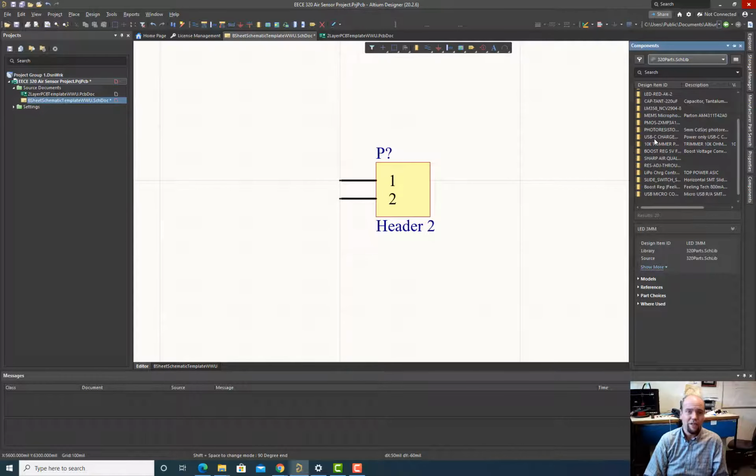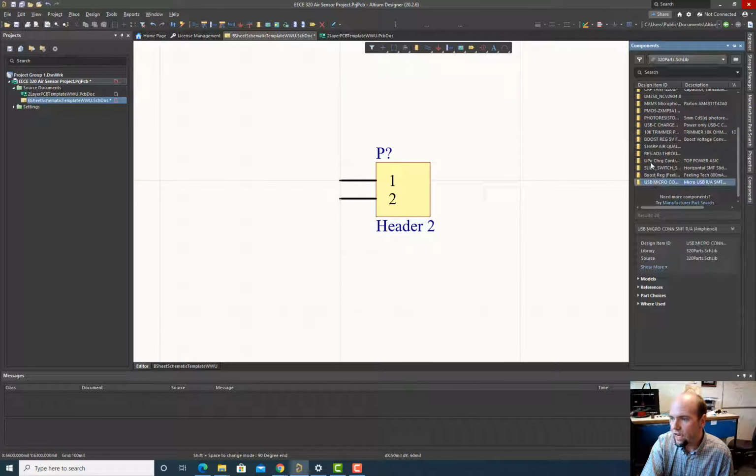So we could just take the USB-C connector, which is a nice clean 5 volts coming off USB-C, and power our circuit directly. But to add extra functionality for this project, I wanted to have that battery component. It hits more of the outcomes for this class. You learn about how to use battery chargers and boost converters. So for the way we use it, we are going to have that USB-C connector power the battery charger portion of our circuit and really nothing else. So let's add a USB-C connector. Again, schematic library parts, not USB micro, we're going to go to USB-C.